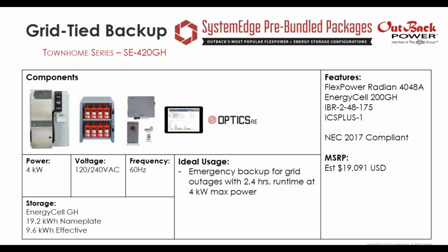But you've got these 8 Energy Cell GH batteries, and these are great for standby systems like this because there's very little self-discharge on these batteries. They'll hold up a long time in a standby mode, and there's not a lot of cycle life in those, so we do want to be careful about that. I wouldn't put these in an off-grid scenario, but if you're just going to use the system for a few days a year, then it's really a great way to go.